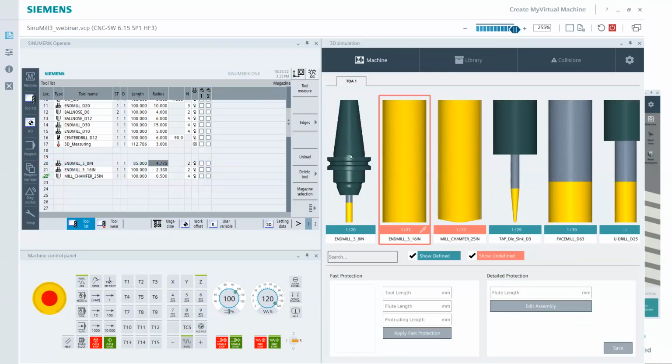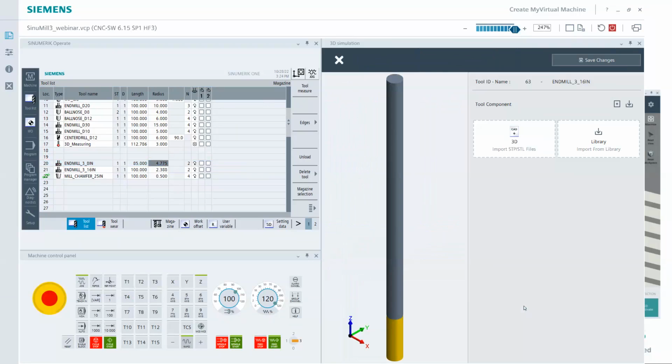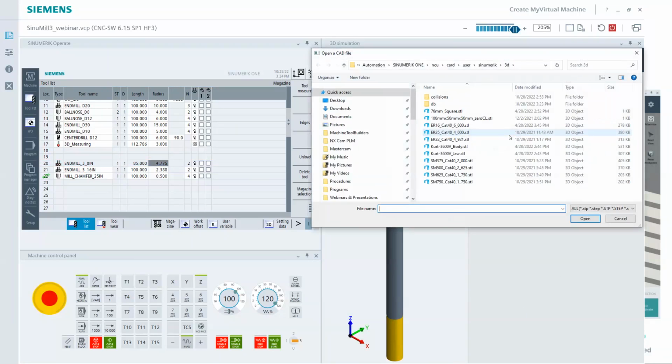The datum's got to be right there. So as we load it into the spindle, you'll see it'll be in the right spot. Now this tool, we're going to do the 3/16 tool. Maybe I want my cut length to be a little smaller, and maybe I'm going to use a collet chuck for that. So you come in, I'm going to use a long projection. Here I got a 6-inch long collet chuck, a little ER16.